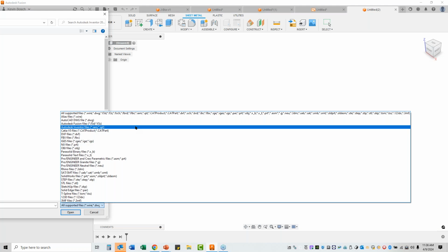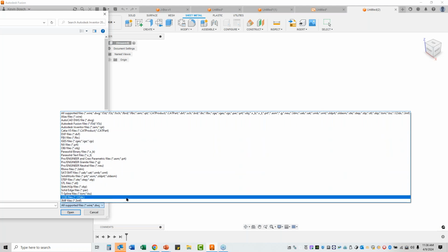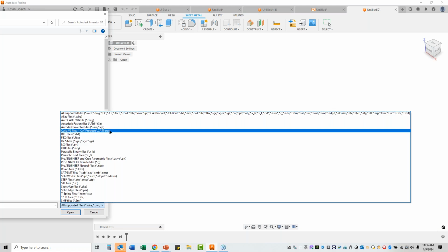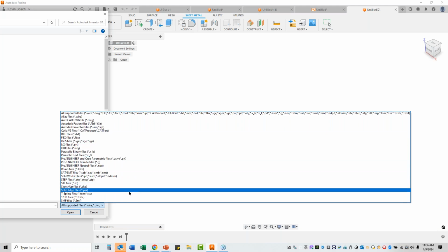Now, when it comes to the drawing sides themselves, such as an AutoCAD drawing, title block, border, all that good stuff, that's a little different setup. You're really wanting to pull information from the model tab as opposed to a view tab where you've got your title blocks and whatnot. And you notice that there's not a DWG or an IDW setup from Inventor. There's not CATIA drawing files or SolidWorks drawing files. These are model files that you're going to be bringing into Fusion. And then obviously you have the drawing environment where you can create drawings for those.